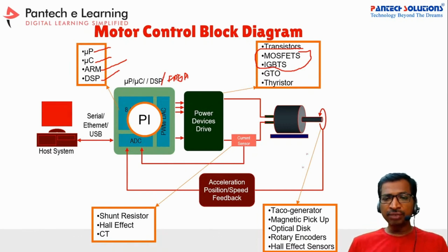Instead of a DC motor, if you use a three-phase induction motor, you are going to use a three-phase inverter with three outputs. The same goes for BLDC, PMSM, and SRM. So this is the generalized speed control mechanism for any motor. Just keep in mind that, based on the motor type, you have to choose the PWM generation logic.